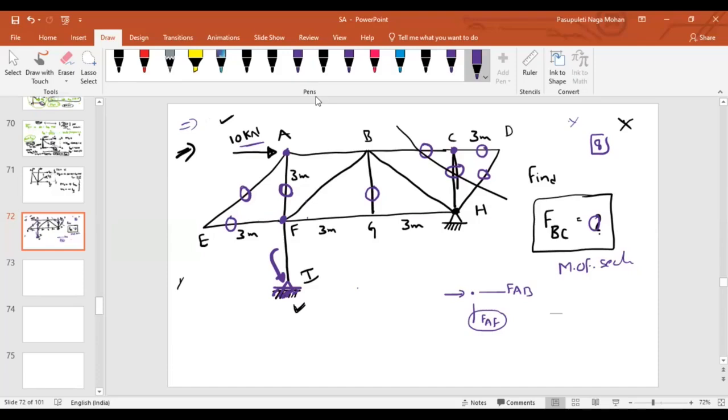So, what is the orientation of this member FI? It is fully oriented along the vertical direction. Right? Yes, sir. It is a truss type of element. If it is a truss type of element, which type of forces will it carry? Axial force only. It will transfer axial forces only, right?